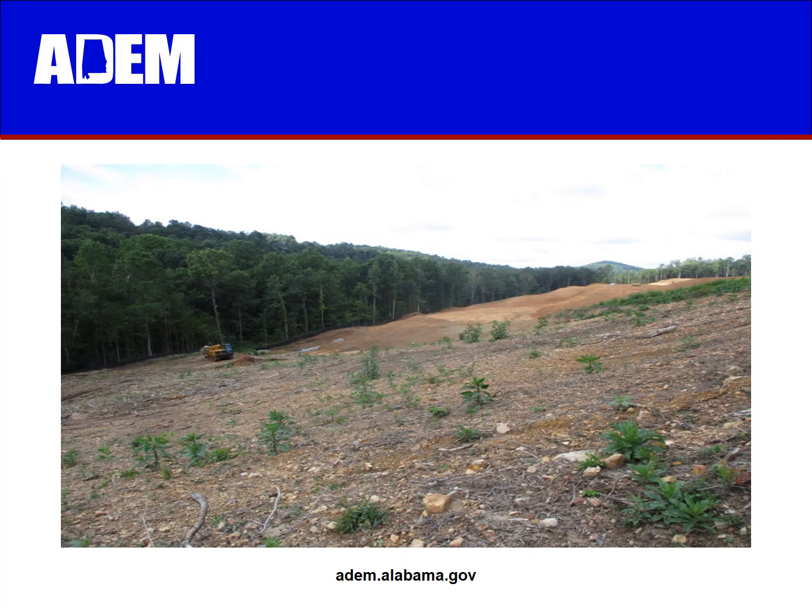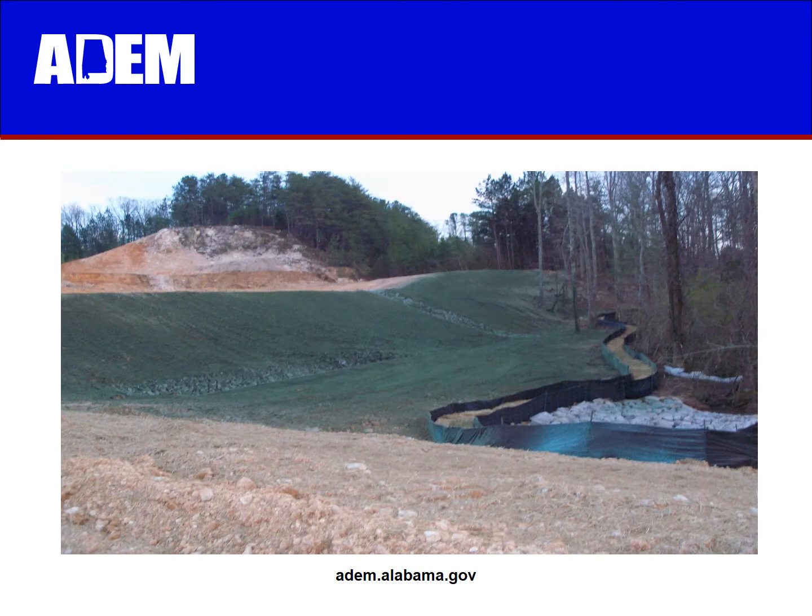Clearing too large of an area and not phasing construction can create unnecessary challenges with keeping soil on site. When large areas must be cleared, hydro seeding and other BMPs can increase your ability to maintain compliance.